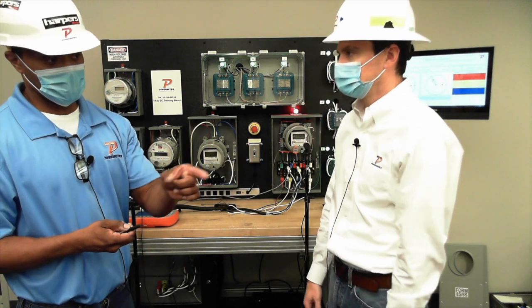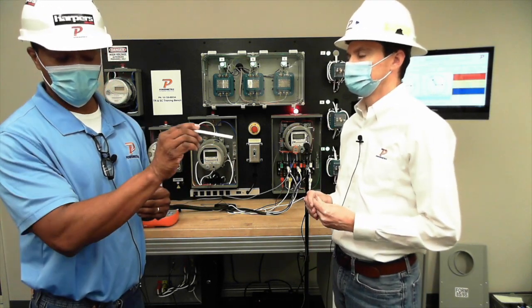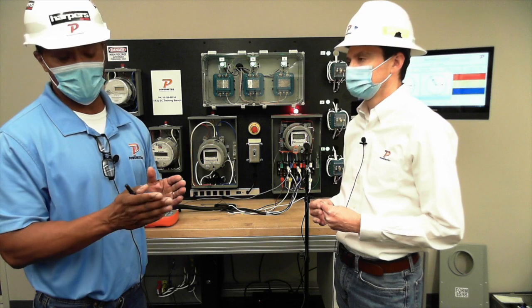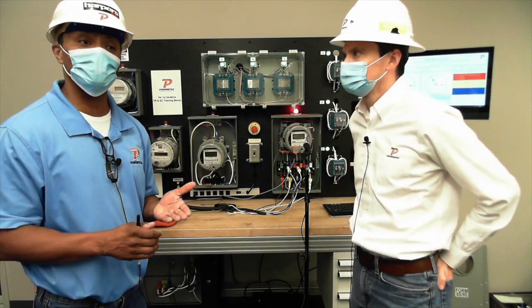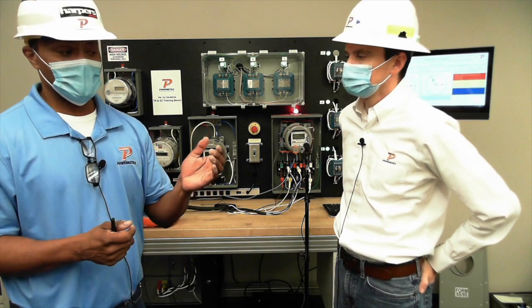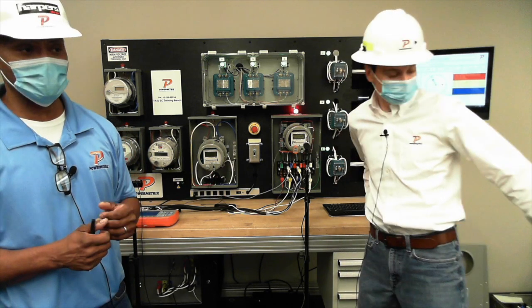Yeah, especially on electromechanical too. Yes. That way you can figure out if that little motor's dragging inside, you might have a dial that's touching the base of the meter that's dragging a little bit. And that's what I was saying. You can actually just browse over and take a look and see what the demand is doing while you're running the test. All right. I think that about does it for demand. You want to move on to register?